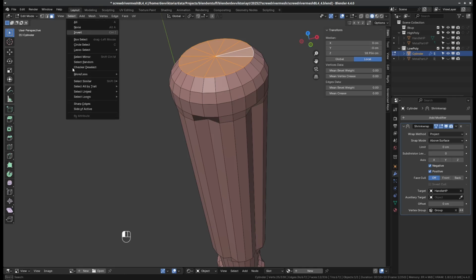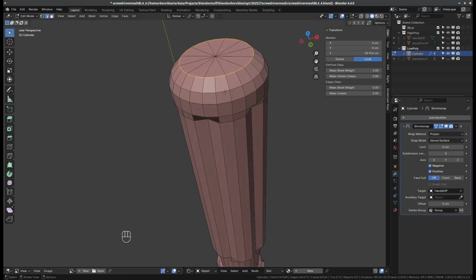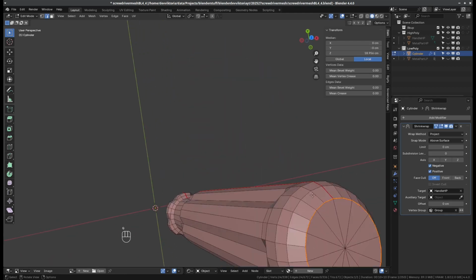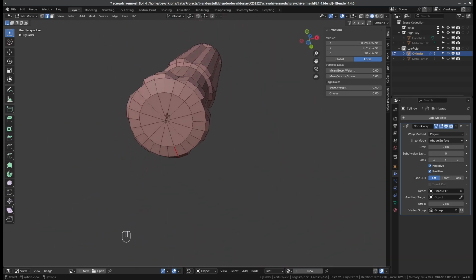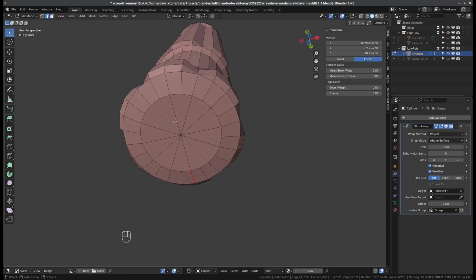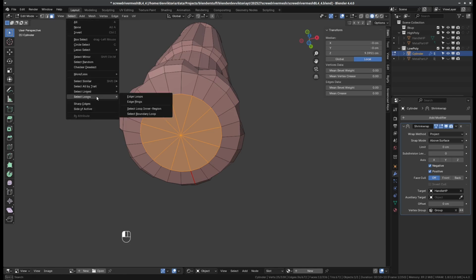And select the boundary loop and then Q mark seam, and I usually like to clear seam just so that it sticks together. Let's see the bottom. Let's hit the escape key and 3, select faces, and now this is okay.